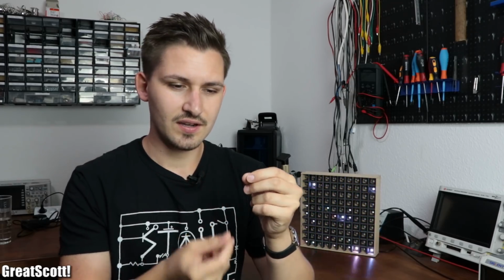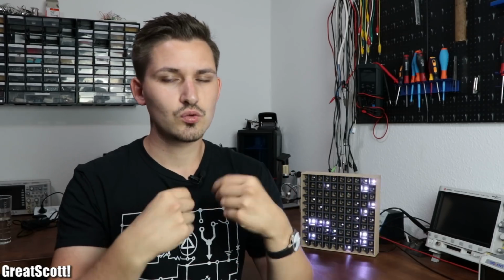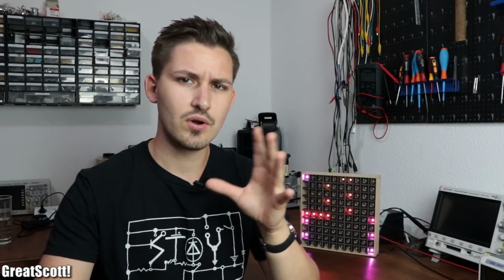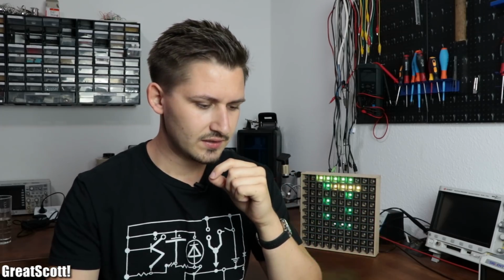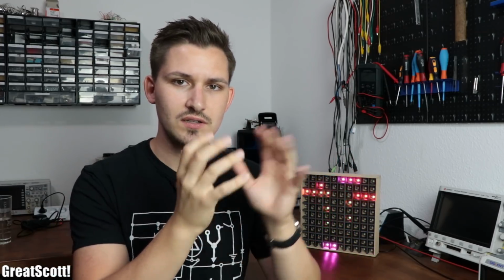So you can just see the voltage of each cell and then swap them out when they're too low, like maybe 3.5 volts or something a bit lower, 3.5, 3.3 volts. And yeah, that would be my solution. Just 2 18650s, the battery holder, then a charger, a BMS, and then the voltage level circuit. That would be my idea. That's how I would do it, because those 18650s, they have great volumetric and gravimetric energy density. I hope that answered your question.